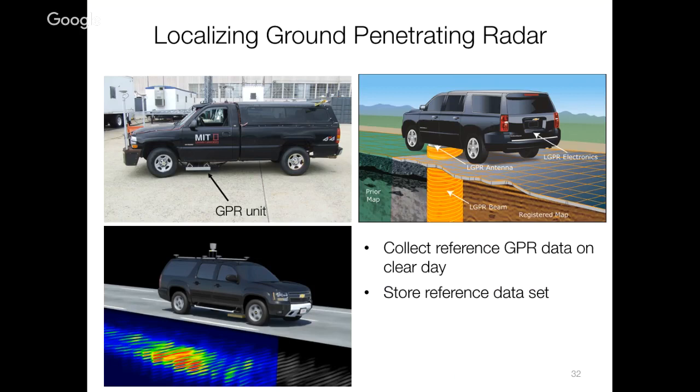Yeah, but your GPR, when someone pulls up next to you, is going to go crazy because it's going to pick up a big metal car. We had some guys who did some work and they forgot to move the Jeep every time they did the GPR. All they saw was the Jeep. They were driving along and picked up the Jeep because it's big metal, and they weren't at the same distance from the Jeep. They didn't spot the mistake until someone else looked at it.